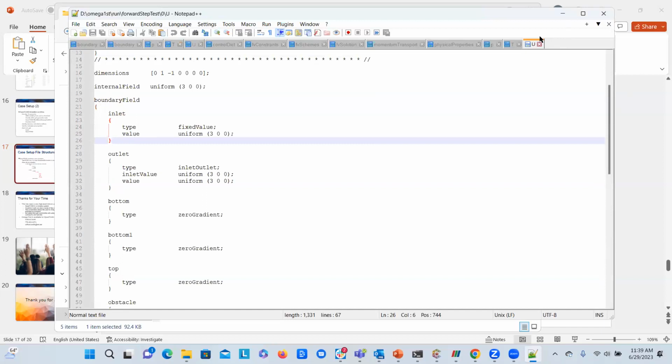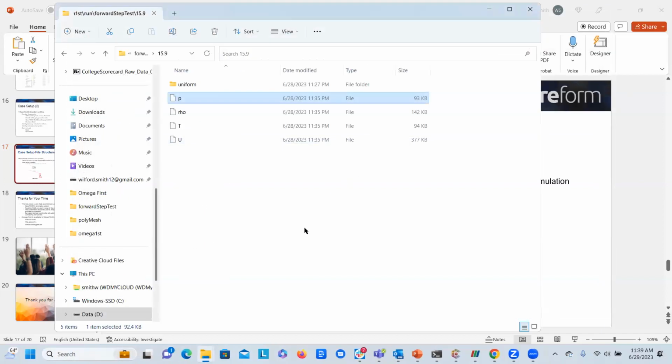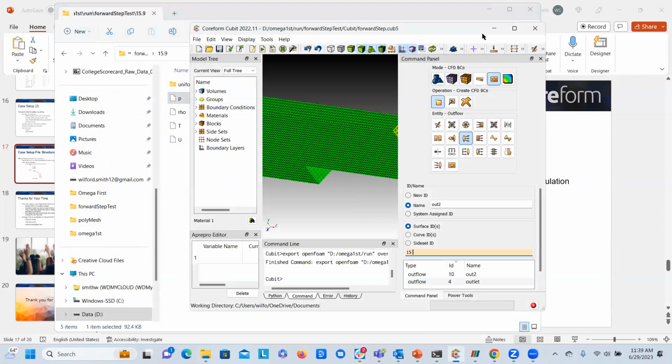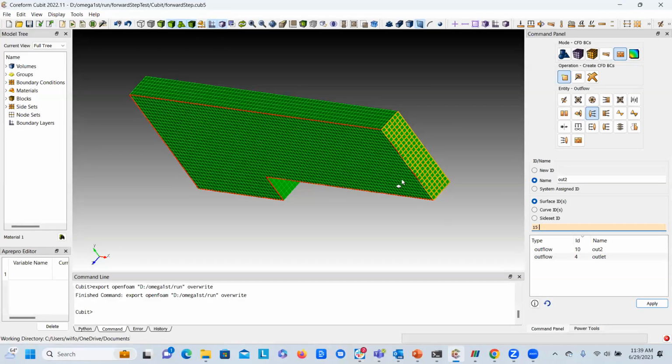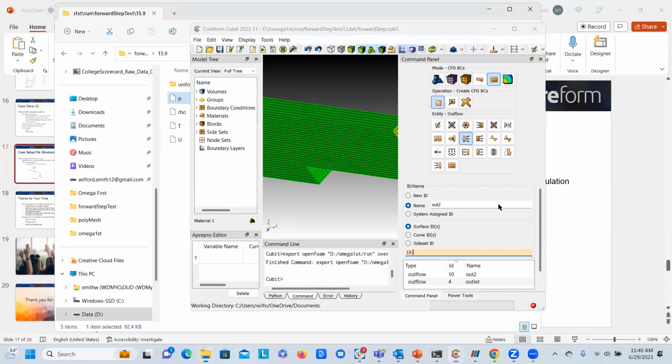Now, as I said, what I would normally do is run the calculation within the Linux partition, and then do my pre-processing and post-processing within the Windows partition. I showed that we pulled in Cubit in the Windows partition and generated our grid, generated our boundary conditions within Windows.